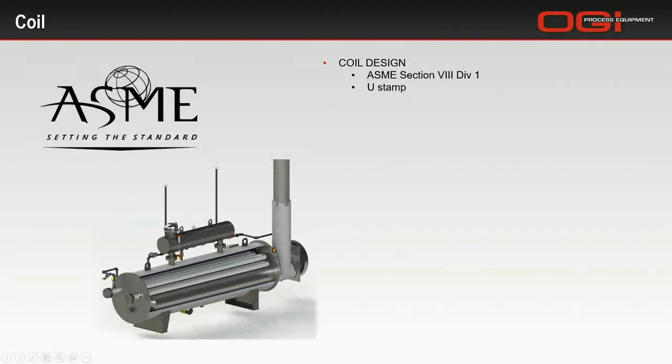And one of the testing that I want to discuss will be your X-ray, your radiography. And you have full radiography, and then you have 100% X-ray. And although the two sound the same, they really are not the same. And ASME allows under UW11 to take certain exemptions. And the exemption I want to highlight is the circumferential welds.